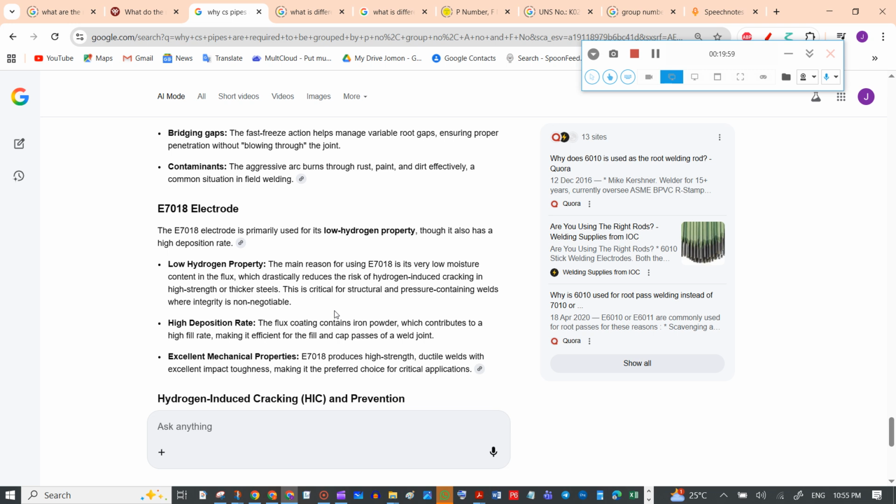But if you are using only 6010, that is for the root pass, its cellulosic coating can give deep penetration and fast freezing so it is useful in the root pass, but it has a problem. Its tensile strength is only 60,000 psi. So to comply with the specification, we need 66,700 for the X52. We are making the weld joints with a combination of E6010 and 7018.